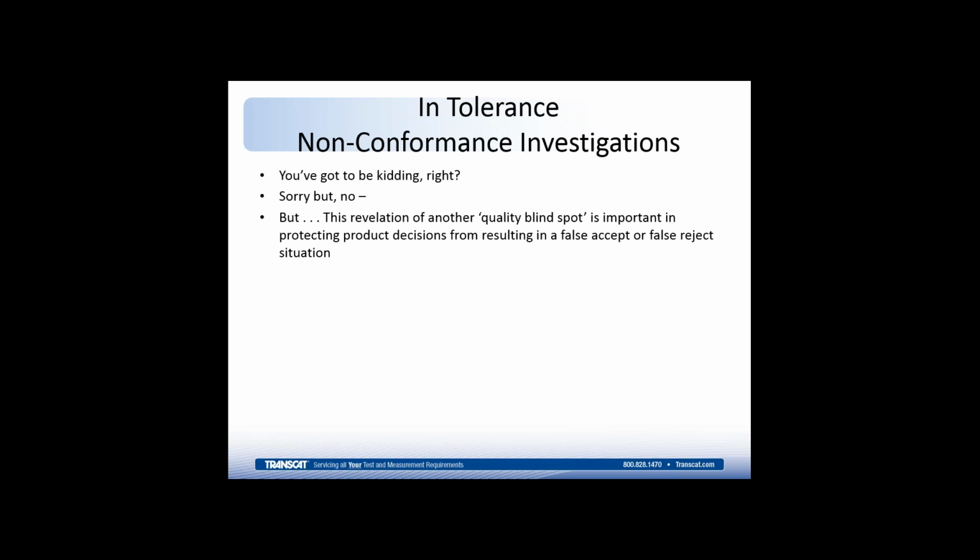This is something that we call a quality blind spot. If you are not familiar with how these numbers line up from calibrating the instrument to the ratios that are used for the standards calibrating your instrument or for the ratio from your instrument to the product tolerances. If those aren't healthy tolerances, you can have situations that are creating a problem with false accept of the product without you even knowing it.